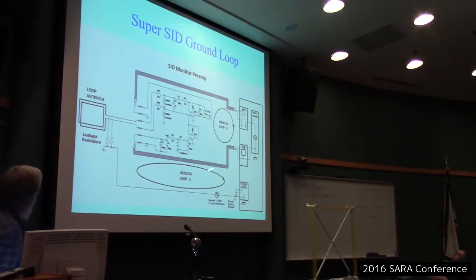So you turn up with a couple of ground loops. First, the power cord to the computer hooks to the earth ground, and if you look at earth ground at any two places, you find that it's got quite a bit of difference. Even two outlets in a house that are near each other but on a different circuit, you can look with a scope between the earth ground on one and the earth ground on the other, and you see there's a lot of trash floating around there.